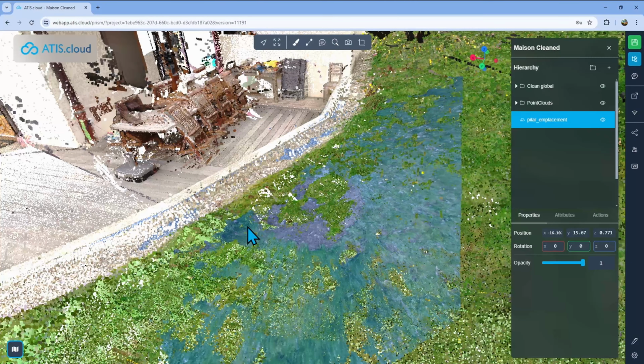I'll select my panel. And so now the only thing I have to do is basically place it on my roof. I'll place that one vertically as it is right over there between the two windows. So what I'll do is first I'll try to put it pretty much in front of it, and then I'll use this double axis to move it around and place it pretty much in the good position. And obviously I'll rotate it for it to have the good rotation, place it, something like that looks pretty good. I might have to rotate it just a bit like this. So I have it perfectly placed, move it around, and so now I have my first panel that is placed.